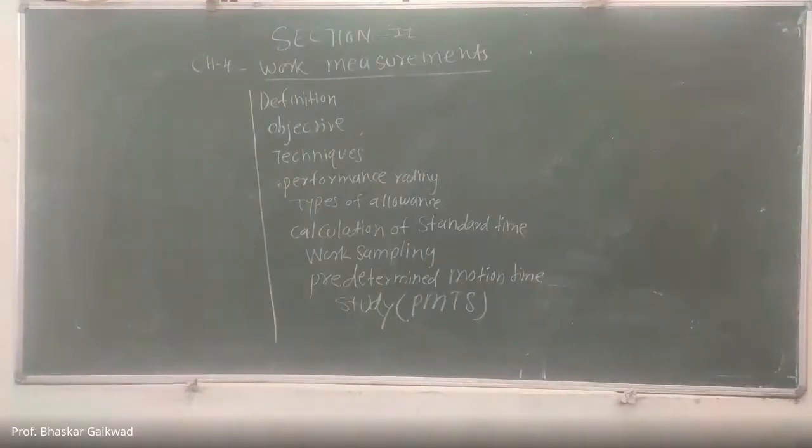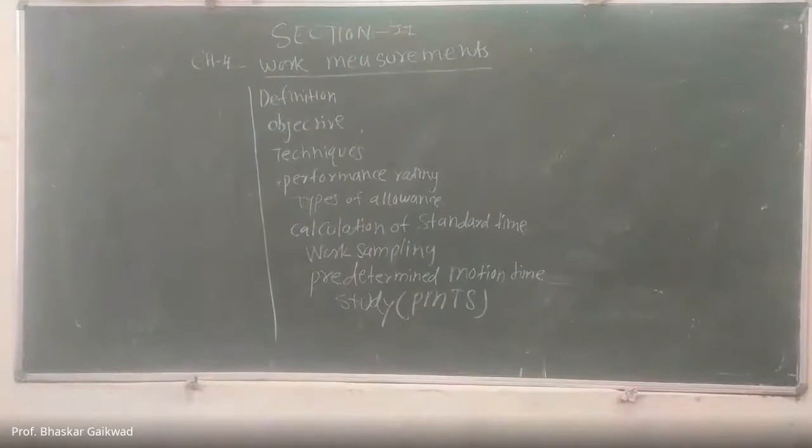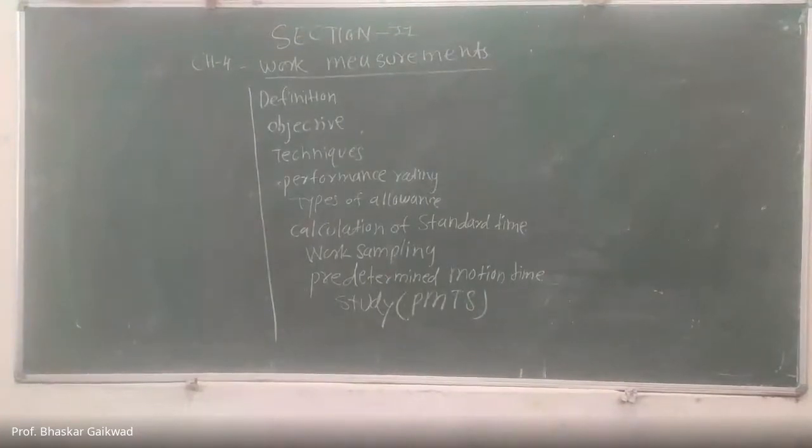Means here, in the 8 hour shift, different types of allowance need to be provided. If you work early morning at 8 o'clock, in the working conditions the person will require certain time for his personal needs, going to the toilet, etc. So that is also the personal allowance.